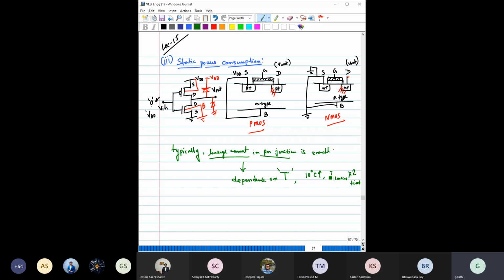And you know, when you are operating a transistor, there will be some power dissipation, and the dissipated power would be radiated as heat, which will raise the device temperature. So the junction temperature would not be at room temperature, but at a higher temperature. If the temperature rises by 60 degrees, then you can imagine how many times you have to multiply to get the leakage current.